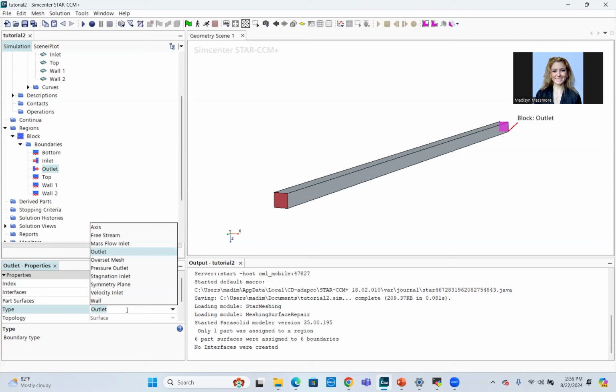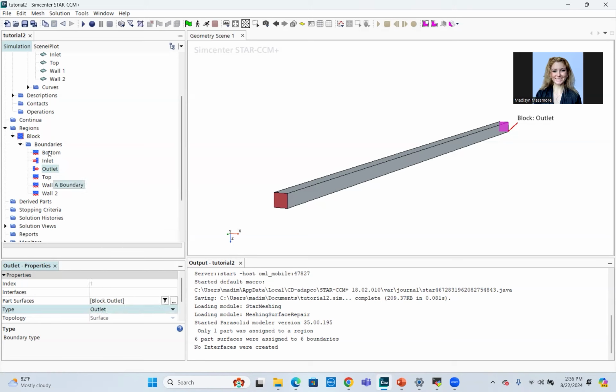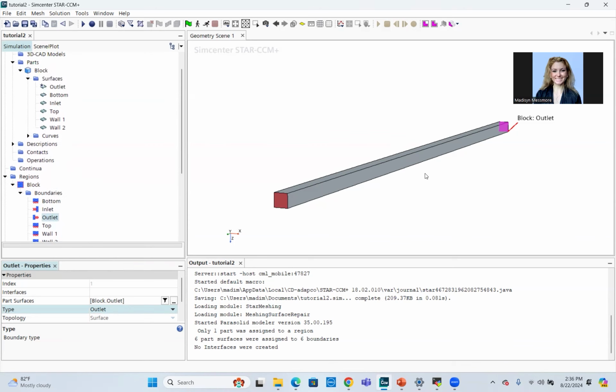And so when you're giving it these properties at inlet and outlet, it is then able to solve those Navier-Stokes equations chunk by chunk, working into the inside. We'll see how it gets turned into chunks in a second, but that's the mesh. So inlet, outlet, we've established these. We'll give them quantities in a bit. That's in general how you set the geometry and all that stuff up. And then, are we assuming steady flow? We'll get to that in just a second.